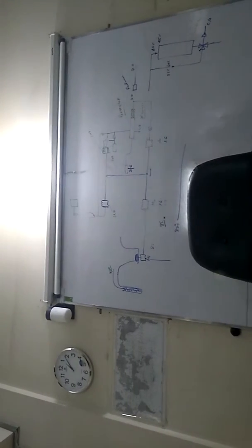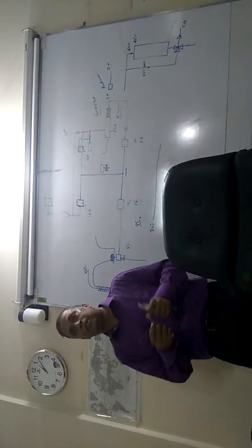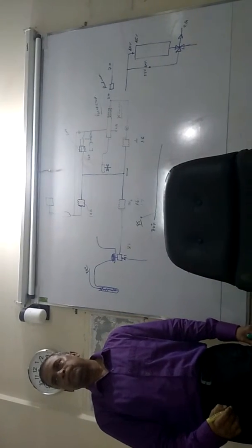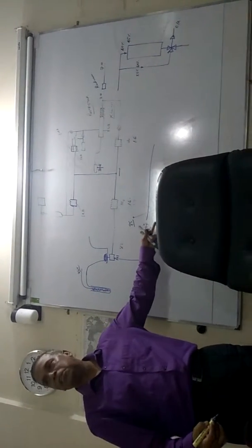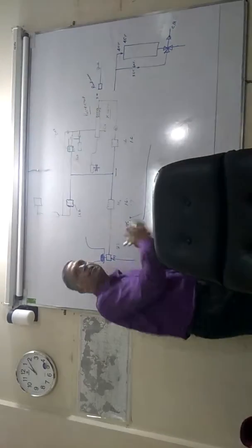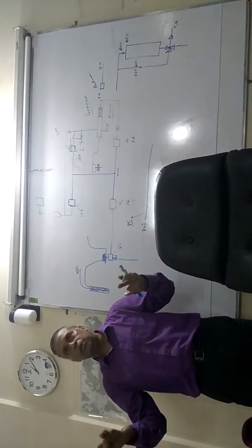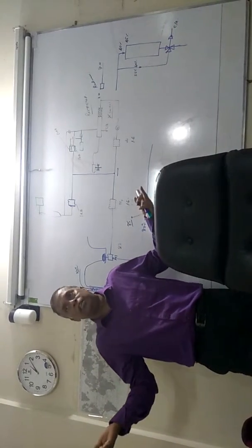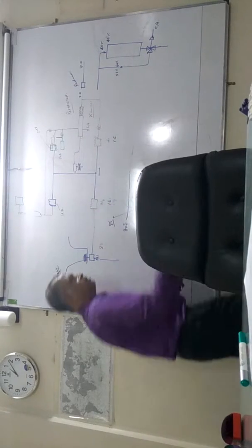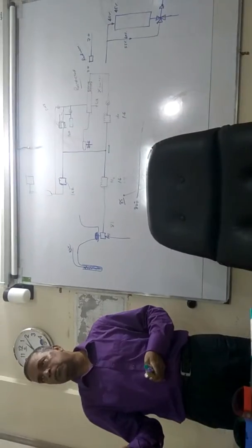So when temperature rise is so fast, or lowering of the temperature is so fast, then it doesn't stop at 80, it goes down. It goes down to 77, 78, something like that. And then suddenly the controller says, oh, the deviation is on the other side. So again a corrective action will come, which is in proportion, you know already. So that is also fast. So it will go like this, like this, like this, until it will settle down. Understand? That is the problem with fast operation of the controller.